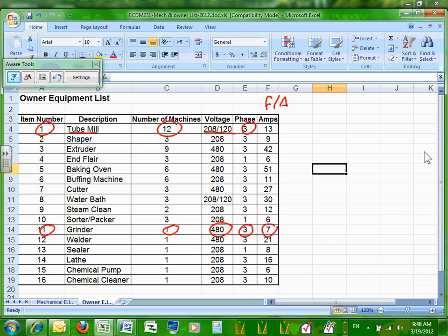So if you're looking at them, can you guys see that there are 2 voltage levels that I'm burning these equipment at? Which means as we design the bus duct, there will be 2 bus ducts. One for the 208 and one for the 480, right? That's why we have 2 bus ducts, because we have 2 sets of machines. The most important thing, guys, is right in here.